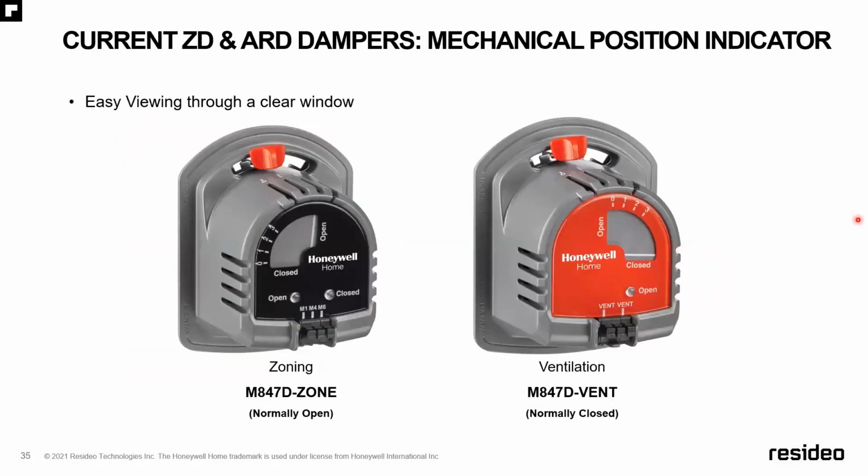It's got many attributes that you're going to really like, that red lever being one of them. But keep in mind that by this damper being spring open, if it's going to fail, it's going to more than likely fail in the open position, which is going to prevent a crisis from cropping up as far as those weekend or late night calls.